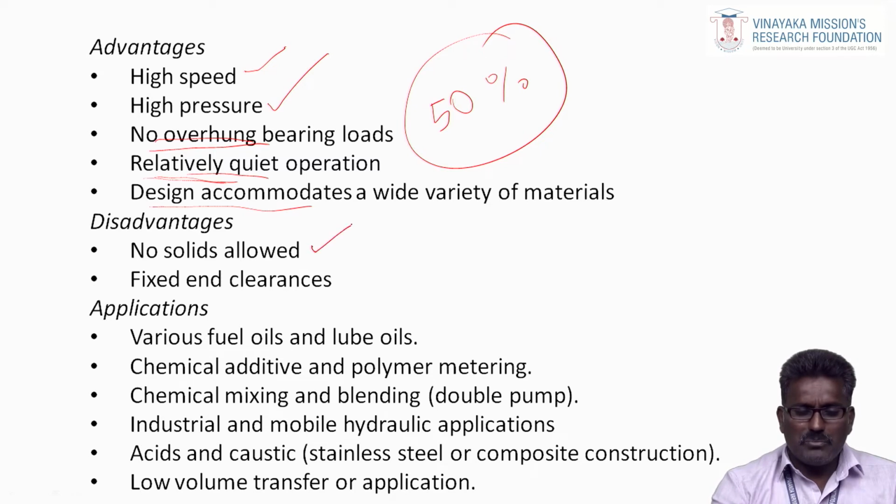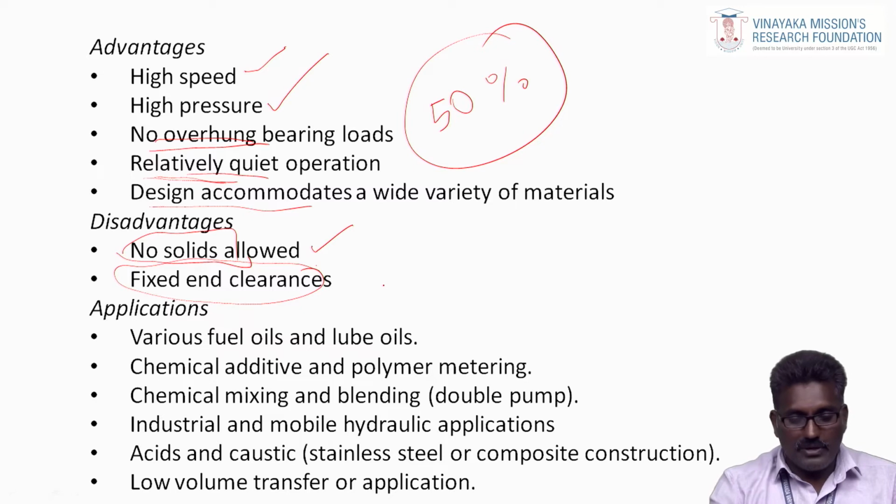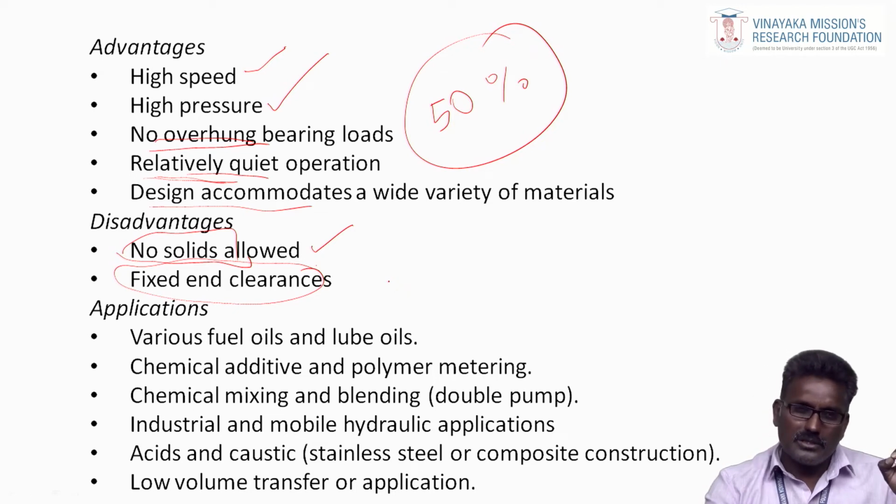So this pump is not able to handle solids. It handles semi-solids, but not solids, and it has a fixed tip clearance. So, that is all. In this pump we are not able to adjust the quantity of fluid. Only a constant quantity of fluid is available for each and every revolution. The same quantity of fluid flow is available. We are not able to adjust the quantity of flow.